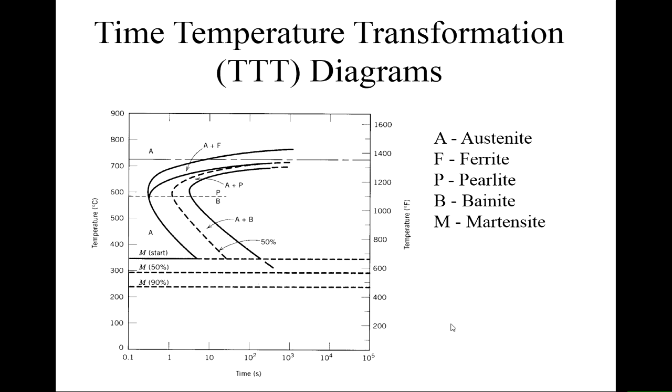And as I mentioned before on this diagram here, if we start off having heated the steel up to more than 900 degrees C so that it has become the austenite phase, if we cool quick enough, we cool down here, we get into this range here where we have this M phase, this martensite phase that's forming.